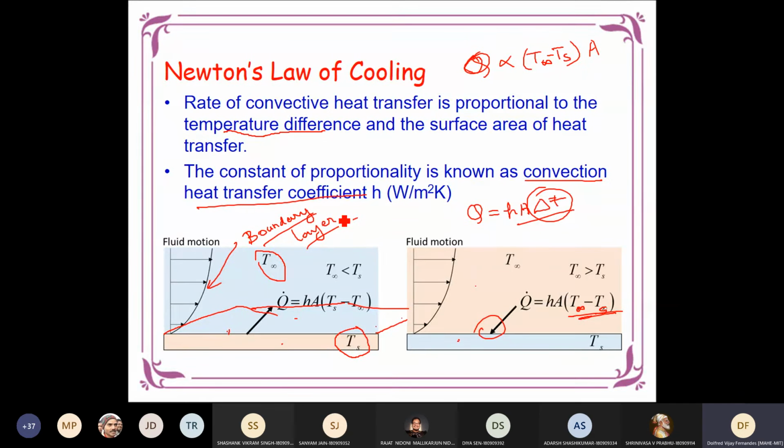Even though we have a large fluid flow, the velocity of the fluid at the surface is very small. So this fluid gets more and more heated, whereas the fluid which is away from the surface will pass over the surface without getting enough heat energy. That means we need proper mixing so that we have more heat transfer.